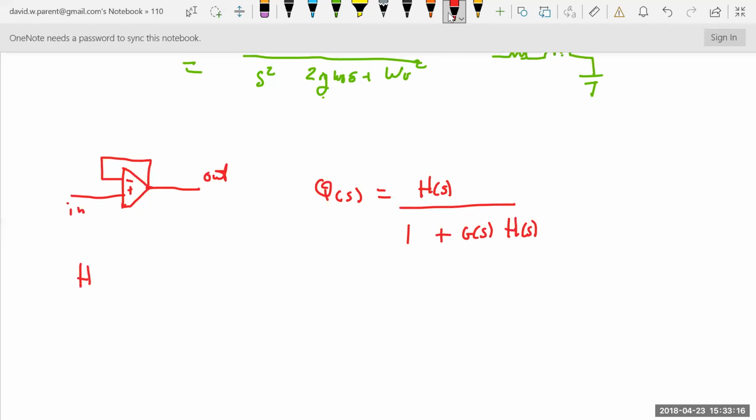All right. The transfer function of the op-amp is the simplest frequency model, 2 pi gain bandwidth, which you would get off the data sheet, divided by S. G of S, in this case, is just 1. Now, maybe there could be resistors there. Maybe I could put a capacitor, resistor, inductor network, right? You can even put another op-amp circuit in the feedback loop, all right?